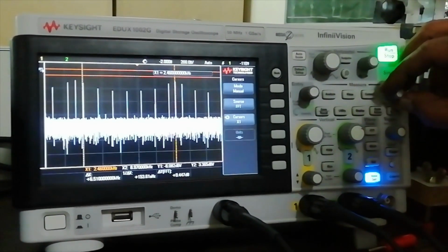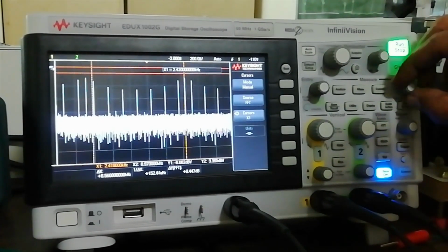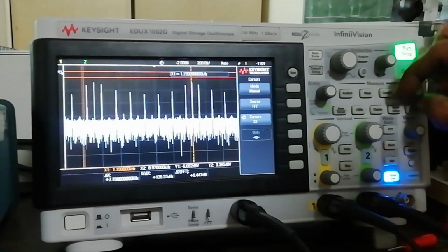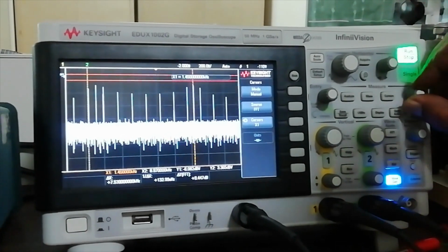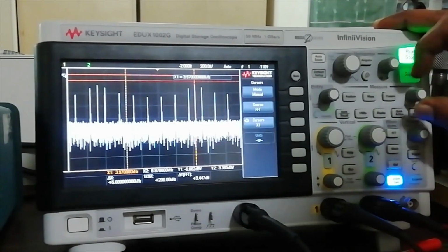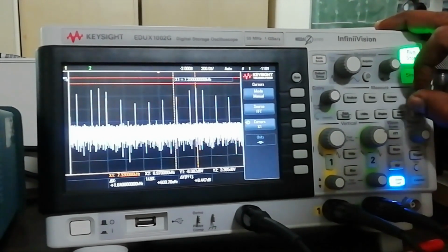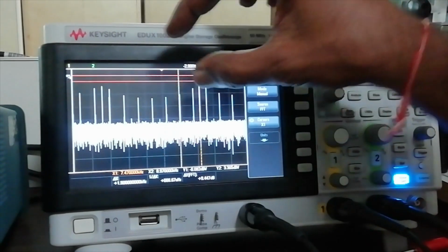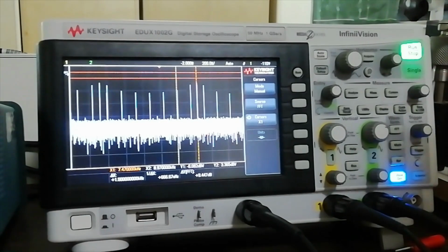Let's take the example of cursor 1. First, second, third, fourth, fifth. These are all sidebands, and if I look carefully, the first upper sideband of 2 kilohertz is 2.5 kilohertz, and the lower sideband of the first fundamental frequency is 500 hertz away from the center frequency. Then the second harmonic is at 1 kilohertz. Rather than 2.5, it is 3.5. Then 4.5, then 5.5, then 6.5, then 7.5. Like that, the entire spectrum is available. The magnitude of the center frequency and the magnitudes of the sidebands do not differ much, so all these sidebands are significant. So the bandwidth of FSK is very large.